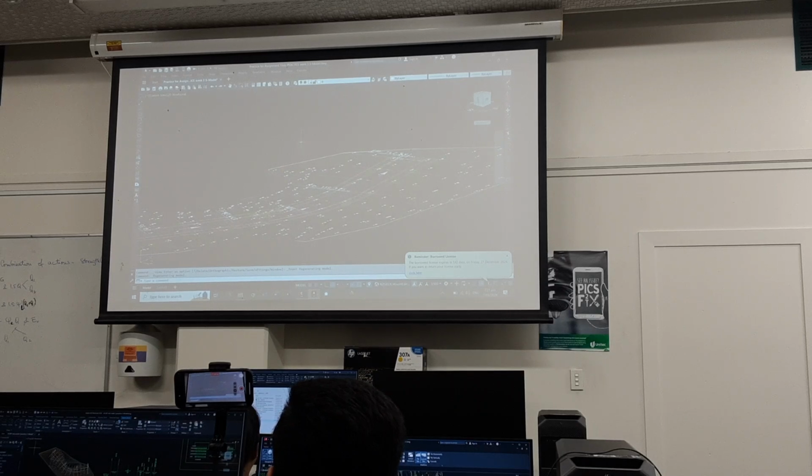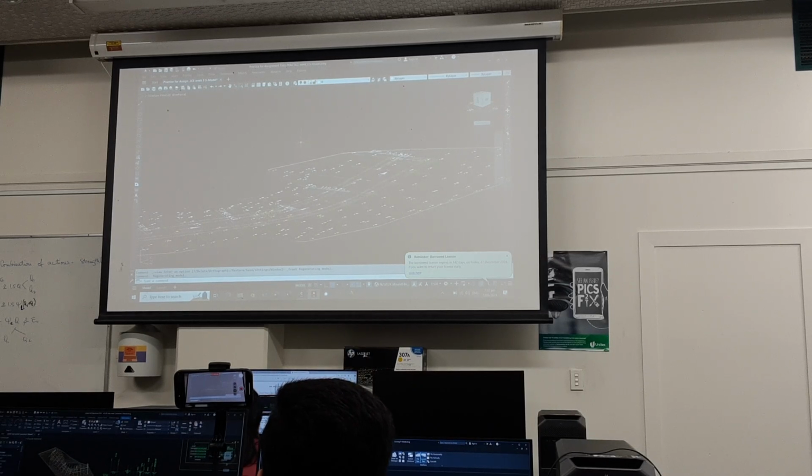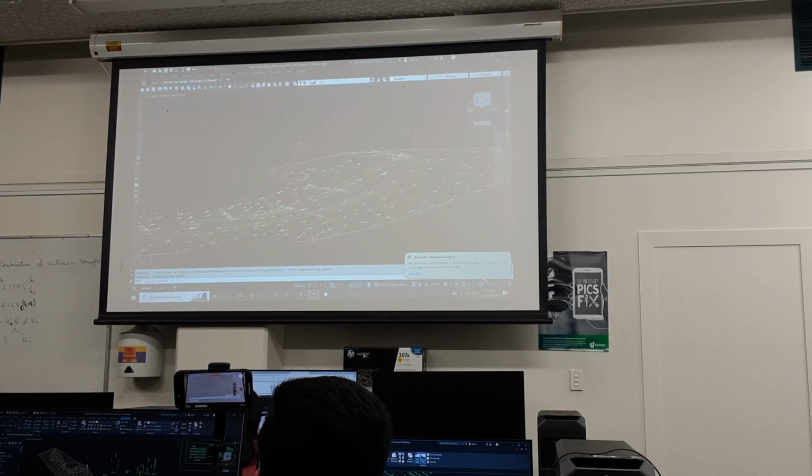Now, if you're doing your existing plan, you don't really want anything on there apart from maybe just a centre line of where the alignment's going to go. So you might like to do things a little bit differently for the assignment, whereby you make it so you can't see the alignment, you turn that off, or you turn the section lines off, the visibility of them.